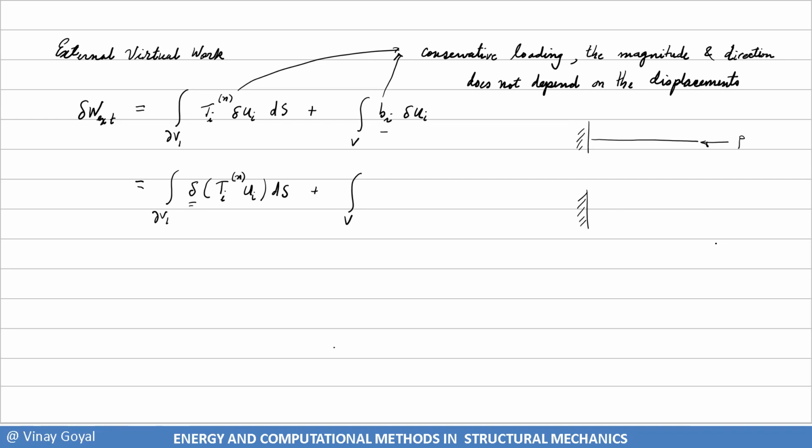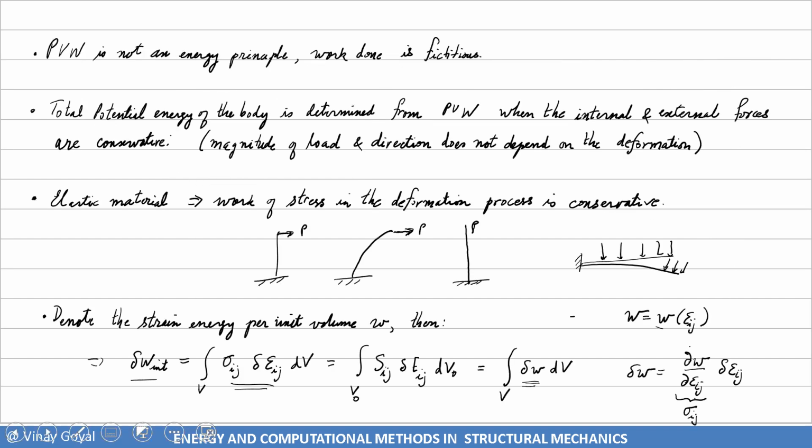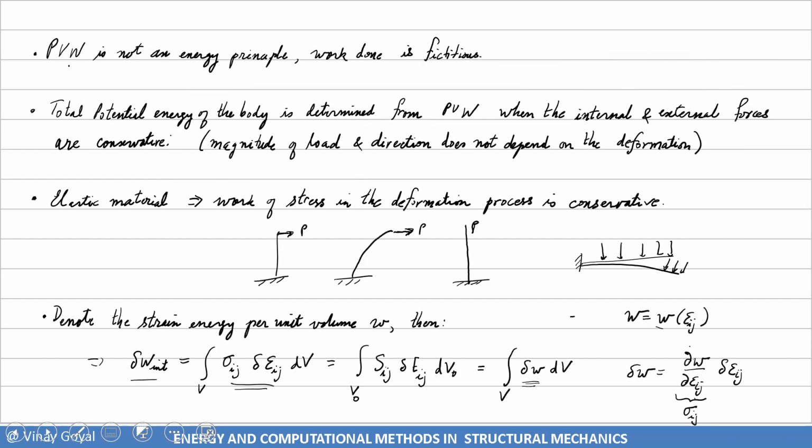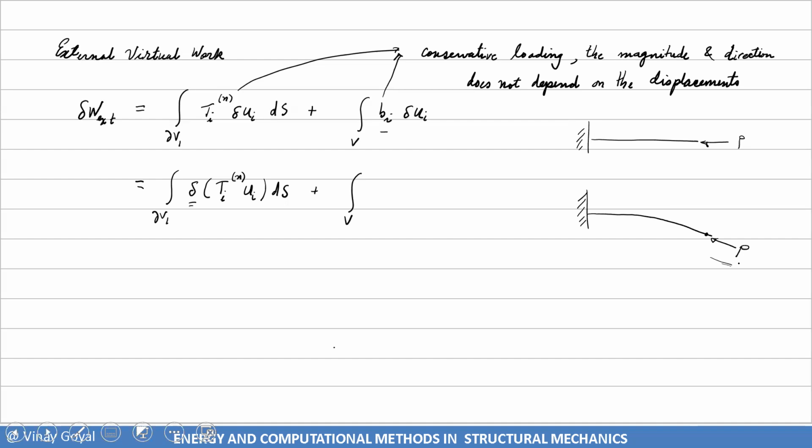If that load P continues to be tangent to that beam, and that's called the Beck's column, then in this situation clearly the load depended upon what the deflection was here, which means I cannot use this idea of conservative deformation system and conservative loading. I have to stick to principle of virtual work at that point, which is more general, is more correct.